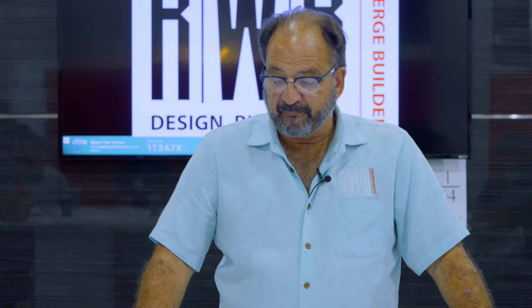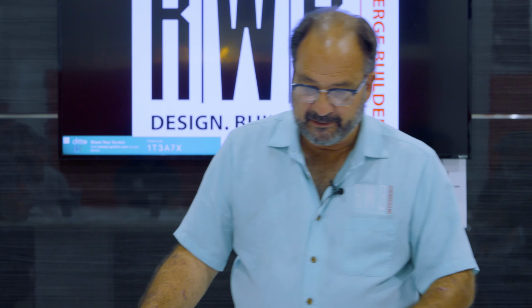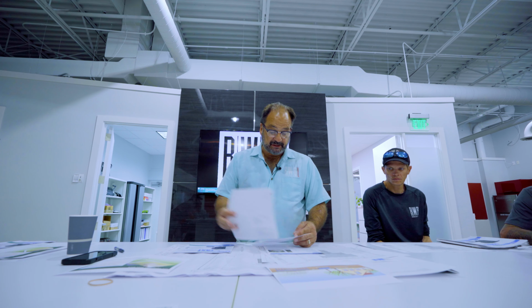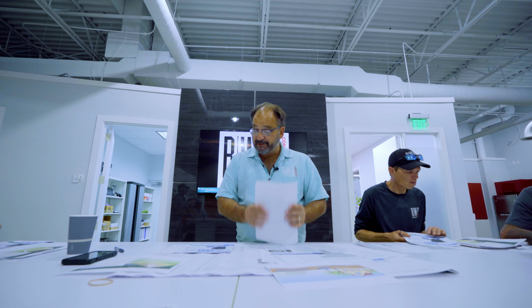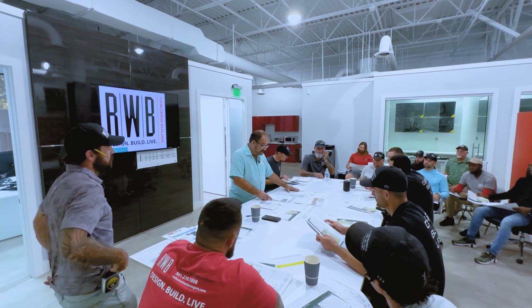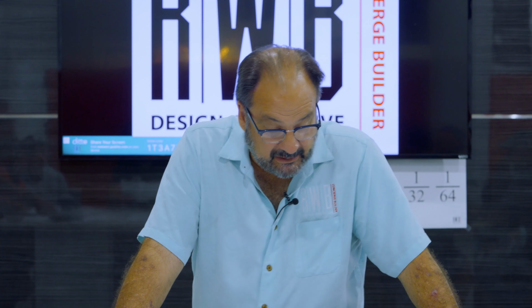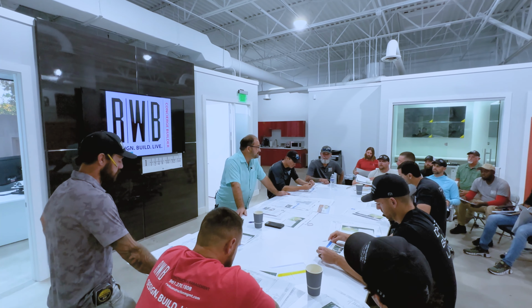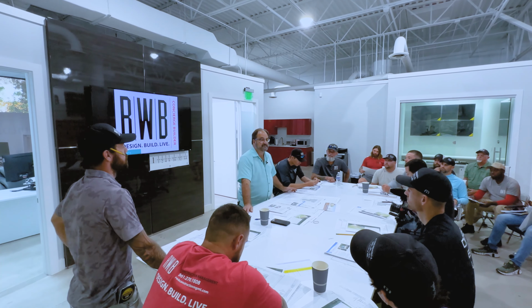Okay, so I've printed you up a few things to take home and look at. I've printed you up some information on grades, walls, the system. We had discussed last week very quickly NAVD and NGVD. Okay, these are standard elevations set by FEMA and the DEP. When you go to get your surveyor in, he will give you an elevation that you will hold as the standard for the job.